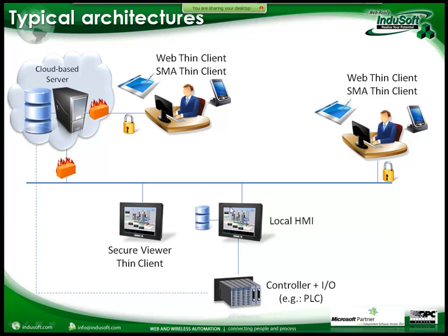So having InduSoft Web Studio running at each site, in addition to InduSoft Web Studio running on the cloud, provides you with the store locally and forward to the cloud feature. So even if the link between the cloud server and the local site is lost for a few minutes or hours or days, you do not lose the data, because the local version of InduSoft keeps saving data locally and eventually pushes this data to the cloud server, and then this information is available to any thin client that connects to the server.